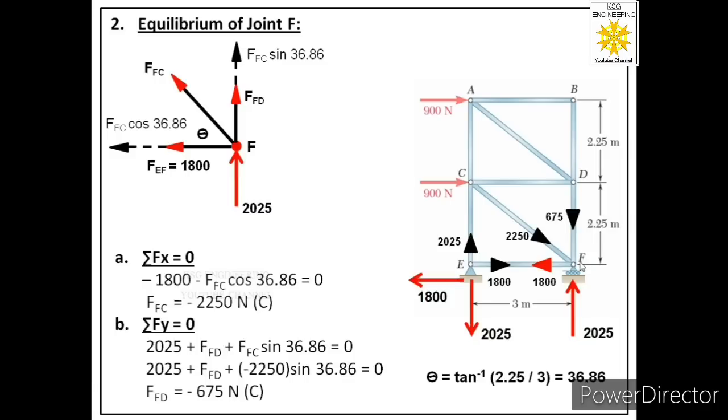Now after this we have to pick the next immediate joint. So we have solved joint F. To joint F, the next immediate joints are joint D and joint C. So let us see with which joint we can start. Let us first observe joint D. To joint D, four members are connected, and this member is a known member to us, but still there are three unknown members. It means at joint D there are three unknowns. It means we cannot start with joint D.